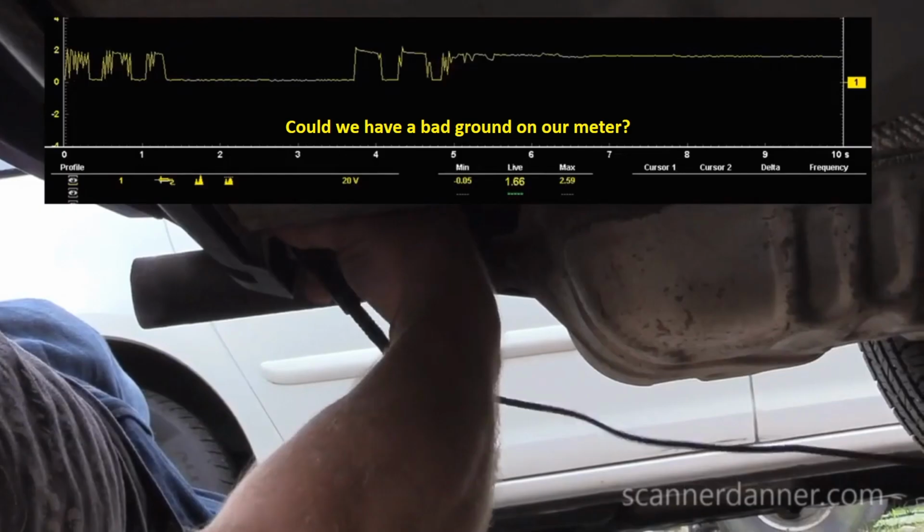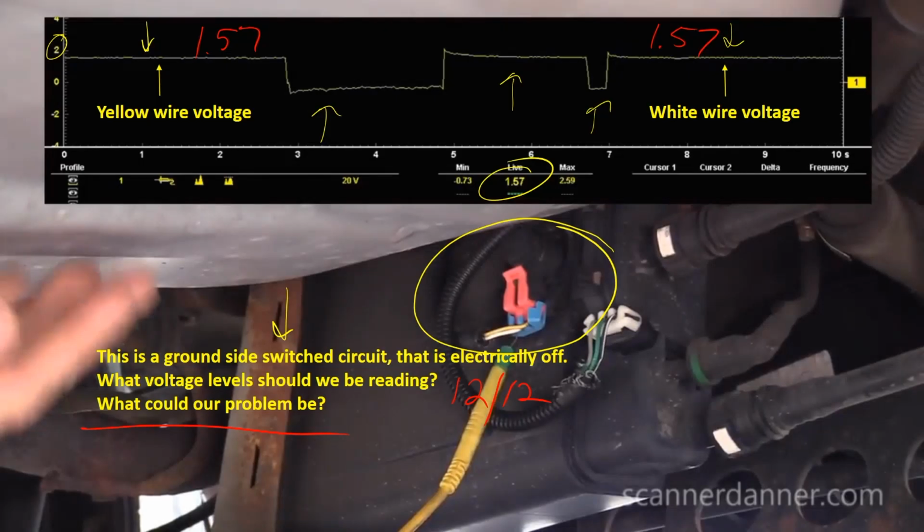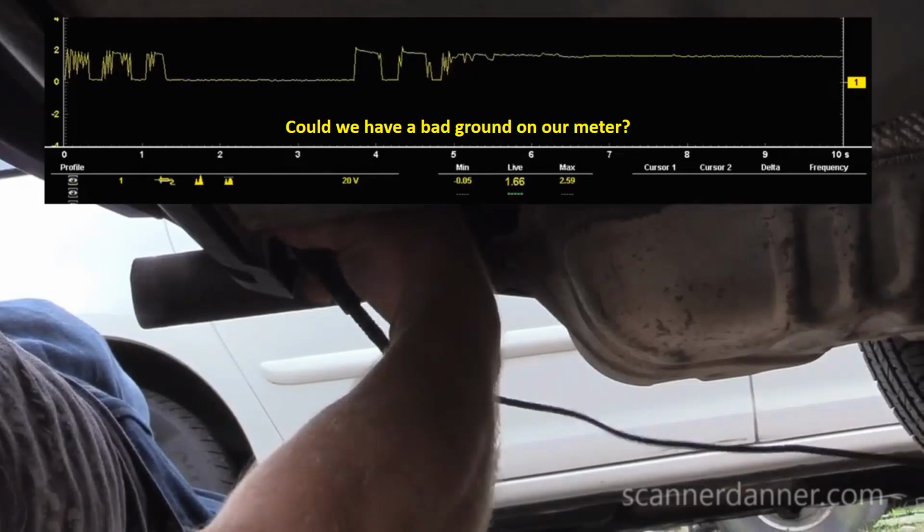I'm moving this ground to different locations, and I'm just telling you that I didn't have the ability to check something known, because this also had a pressure sensor fault, and that was right here. I actually went over to the pressure sensor and did some measurements, and it was all messed up too, because there are faults on that circuit too. So I couldn't use that as my guide, and I just moved to different locations. Just take my word for it, the ground is good. That's what I'm doing here.